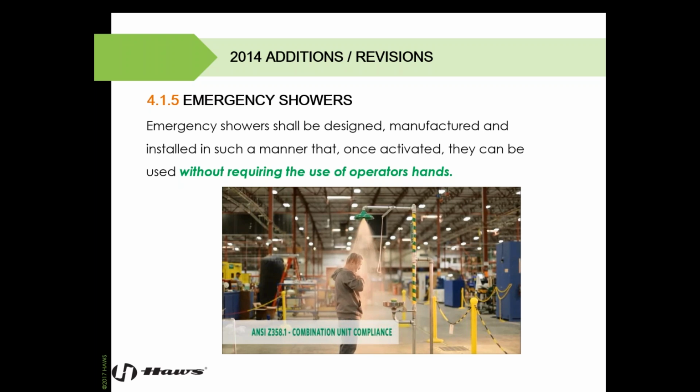So visually in this video, you can see the gentleman activated the shower, the eye wash, and then the shower, and those units are staying on at the proper flow for a full 15 minutes. So he's able to hold open his eyes and remove his contaminated clothing. There is older equipment out there in the industry that has spring-loaded valves that allows the unit to be shut off. So with this revision, you're going to need to make sure that all of your existing equipment is up to date and will stay on without the use of the operator's hands.